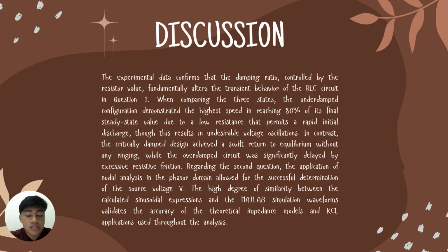Regarding the second question, the application of nodal analysis in the phasor domain allowed for the successful determination of the source voltage V. The high degree of similarity between the calculated sinusoidal expression and the MATLAB simulation waveform validates the accuracy of the theoretical impedance model and KCL application used throughout the analysis.